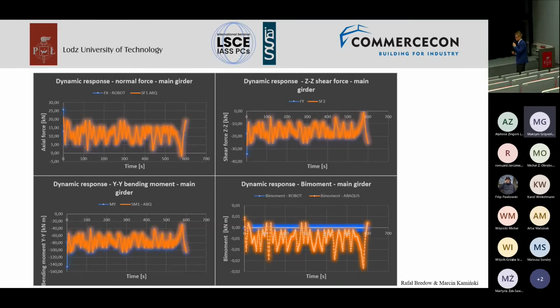Nevertheless, one additional value added to the work which has been performed and presented here is that the output response in Abaqus is also able to recover the moment which is related to the warp. Nevertheless, this influence on the general stress state of those tapered I-beams has been found marginal.